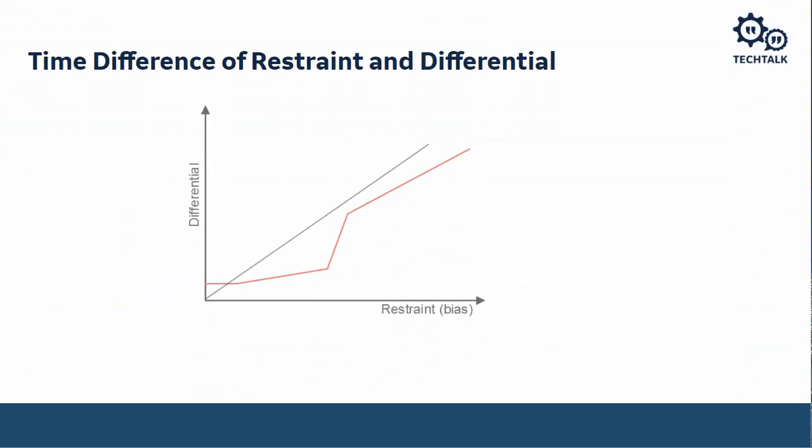So for an internal fault, on slope 1, we're just going to jump into the tripping region, verify the direction, trip, and the fault's cleared. For an external fault, we're going to go from T0 to T1. We're still in the restrained region. If the CT saturates, now it's not giving us an accurate reproduction of the current on that feeder.